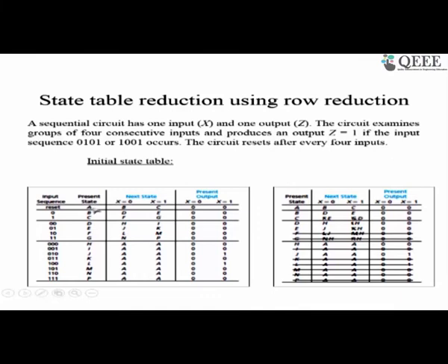Let us say we are in a state A where there is no input bit. When the first bit comes, if 0 comes, let us say we go to a state B. When a 1 comes, we go to a state C. So when in state A, when a 0 comes, we go to B. When a 1 comes, we go to C. This is what we do.